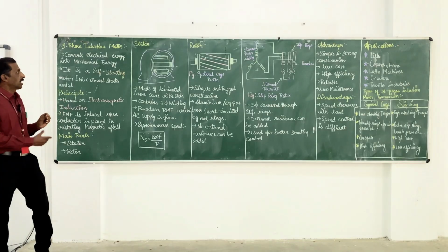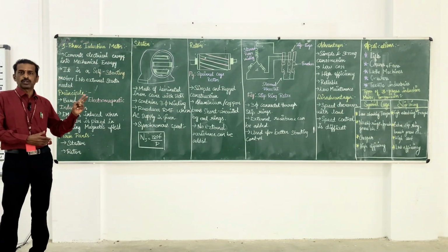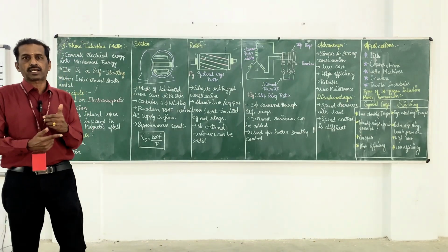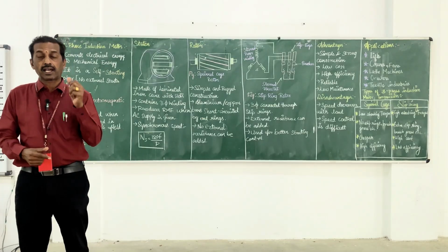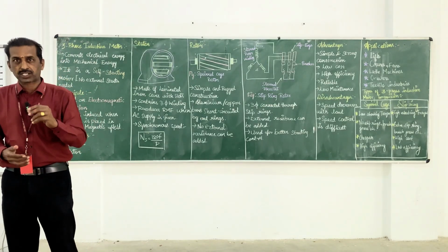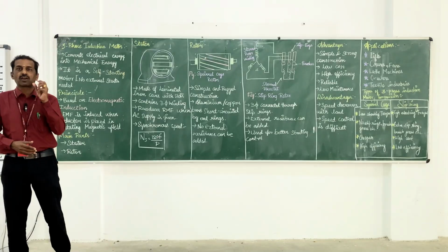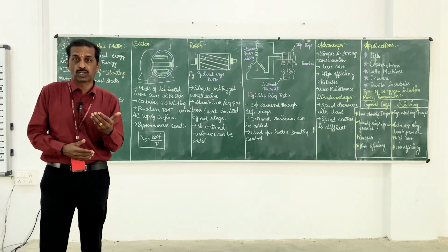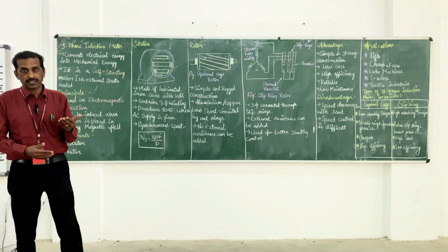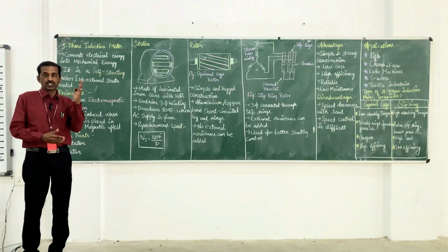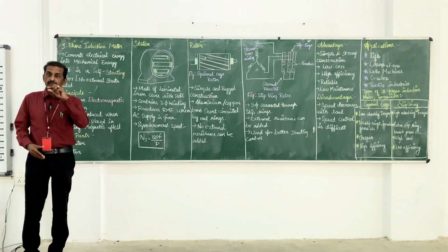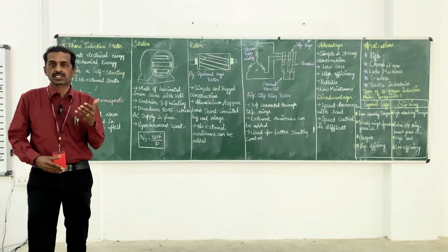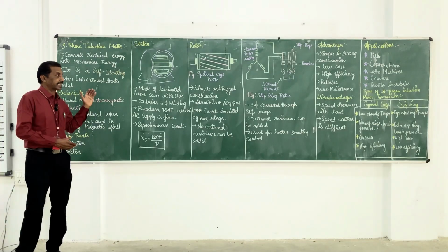Now I am going to discuss the stator side. The stator has the winding part, the body, and the slots. The yoke is constructed of steel because of its high mechanical strength and also for protection. The stator core uses silicon steel material because it reduces losses. Then the stator slots are provided for the three-phase windings. The three windings are connected to the three-phase supply, like this, R, Y, B. So this is the stator side.